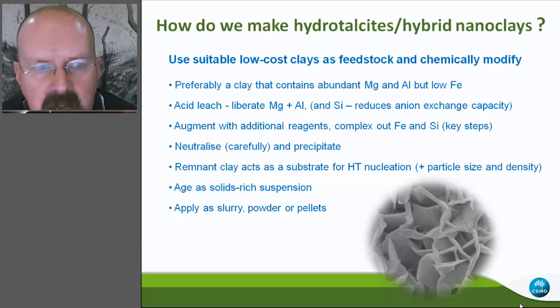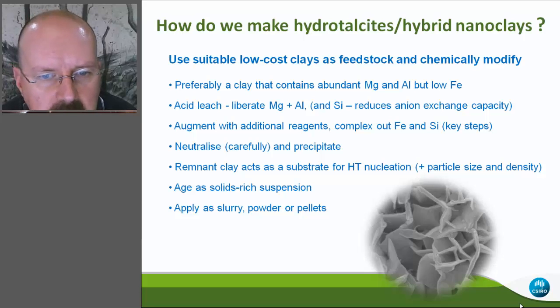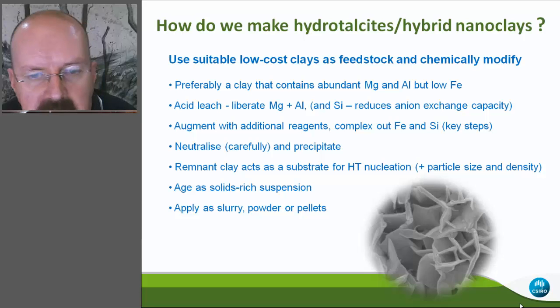We age a suspension of these hybrid nanoclays that we can apply directly to aquatic systems, but we can also apply it as a powder or form pellets as required for a particular application. In the image there in the bottom right, you can see those hydrotalcite layers that I talked about in an earlier slide. You can see the individual layers there. Between them is where the anions exchange into, and they often aggregate, as you can see there. So individual platelets of those hydrotalcites and clays actually aggregate into substantially larger particles.